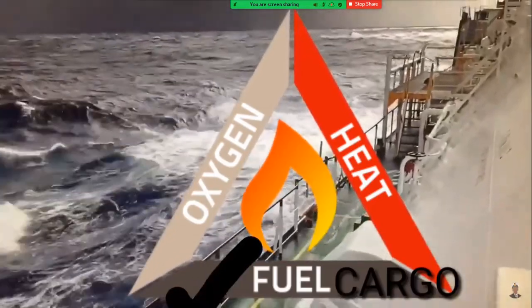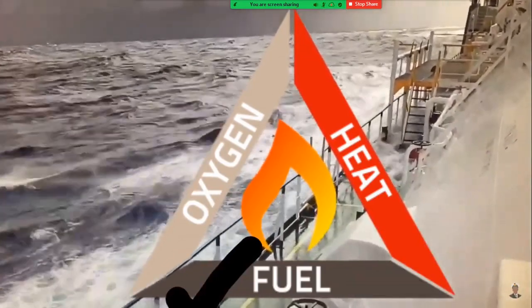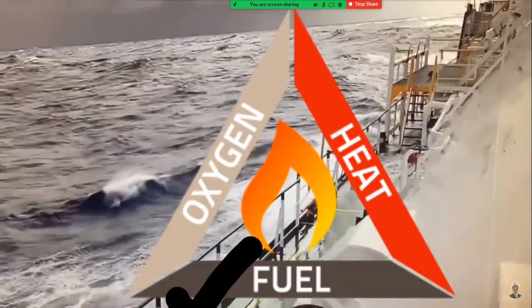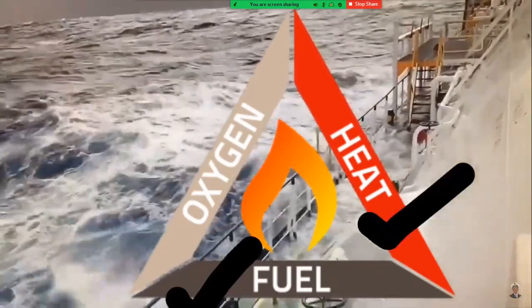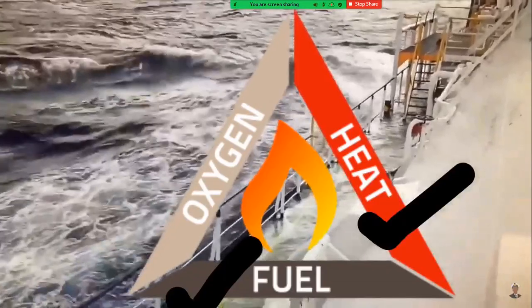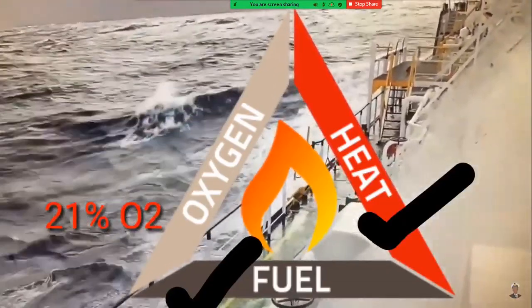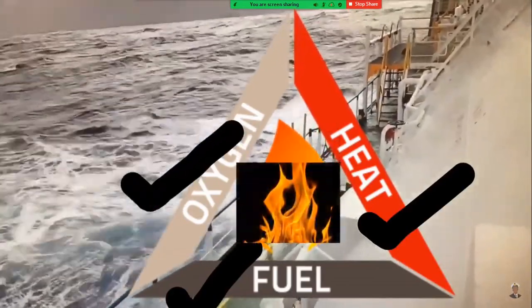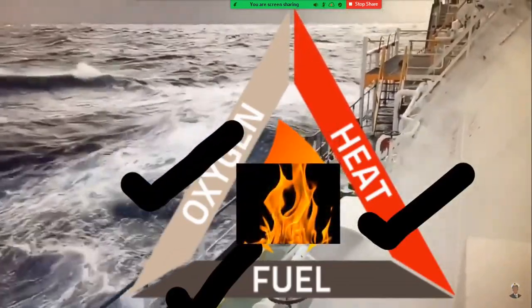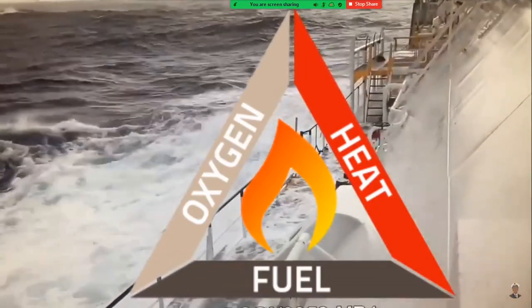Any spark, heat from the adjacent compartment or from hot work, or even atmospheric heat can act as a source of heat in the tank. The atmosphere, containing 21% oxygen, provides sufficient oxygen for the fire triangle to complete and a fire hazard to take place. Removing any one side of the fire triangle will be an effective step to prevent fire hazard on board a ship.